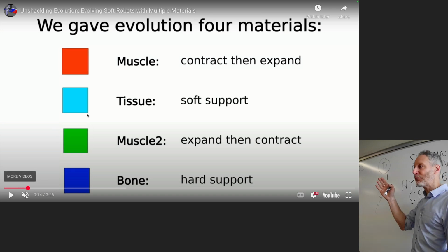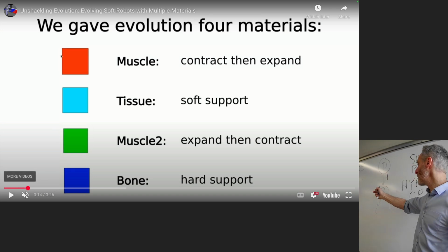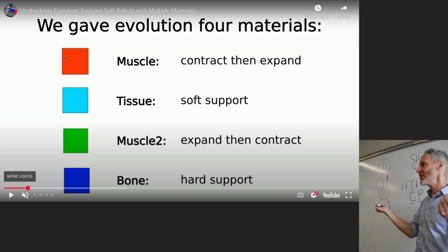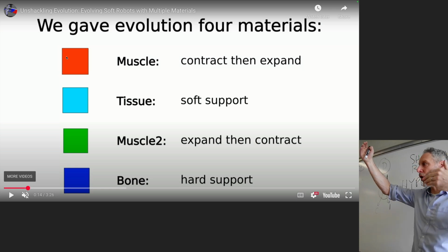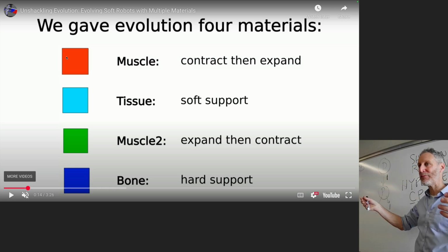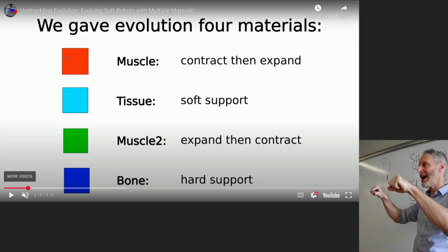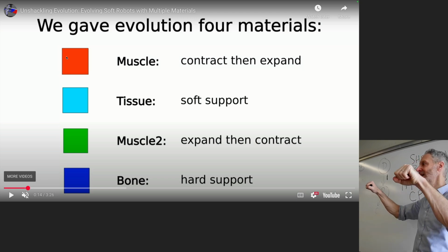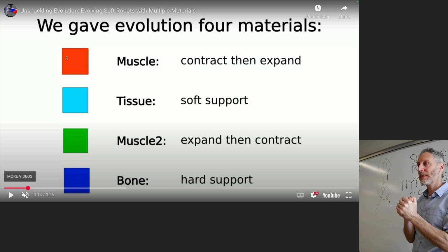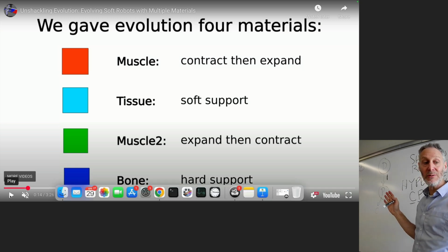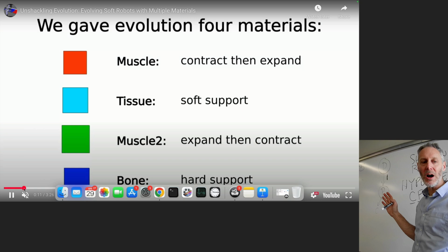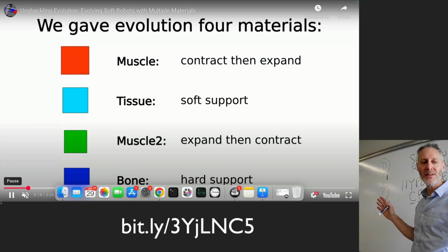What this means is that for these voxels, if the CPPN paints red onto any one voxel, and that red voxel has neighbors, that red voxel cuts all of its connecting beams in half, turns them into pistons, and sends out sinusoidal patterns to all of its beams that pull and push, extend and contract those pistons. That's visualized in the videos you're going to see in a moment by the voxel itself getting bigger and smaller.